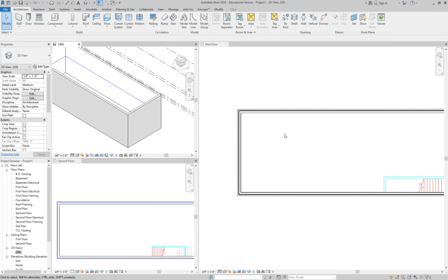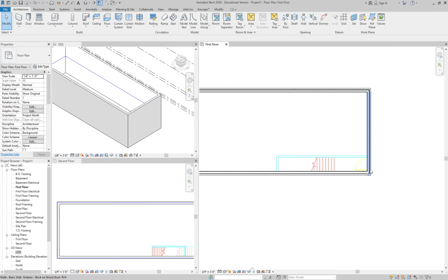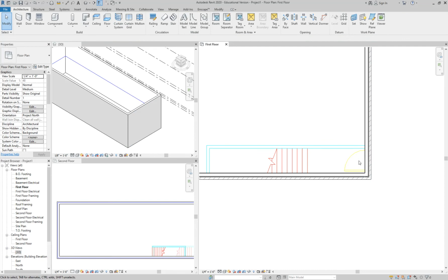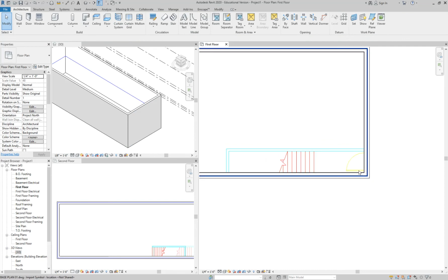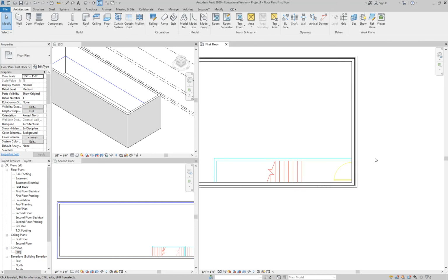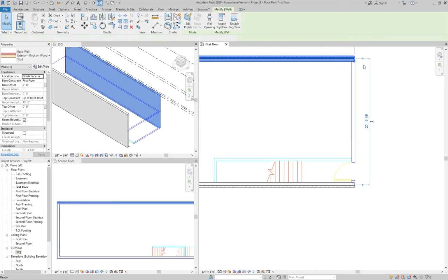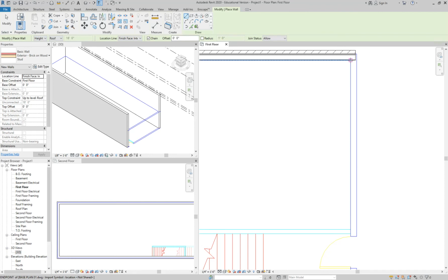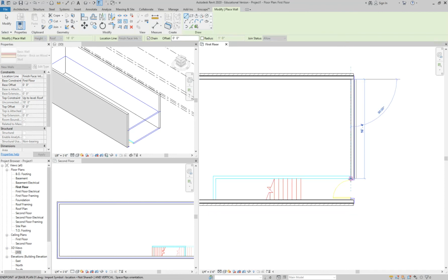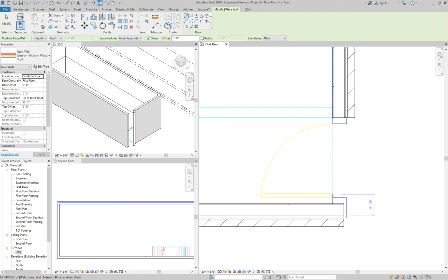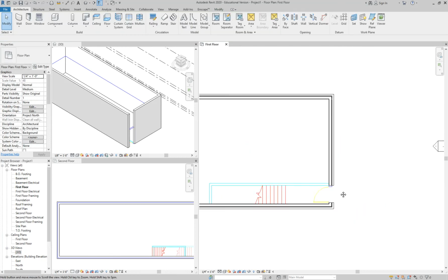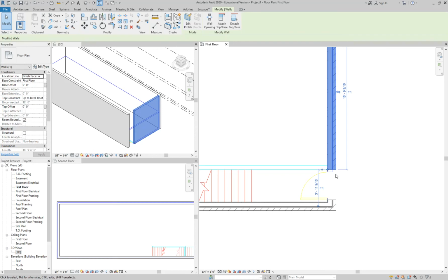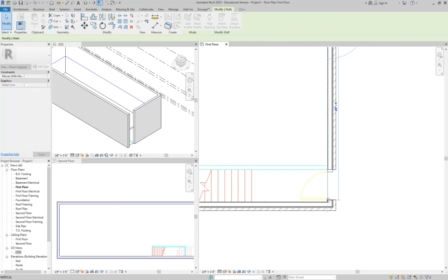So if you did, what I would do is take this end wall down here and delete it and then just do a trim. So you still have one continuous wall. Does that make sense? Say that again. I would rather you do it this way. So here's my interior. I'm going to copy what you did, except I have sloppy tracing. Let's call that good. So if you had it like this, let's see if these two will connect.